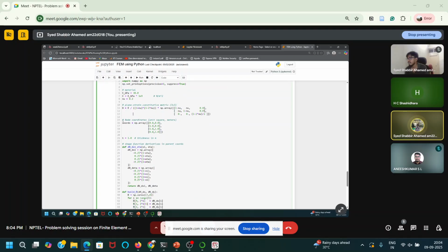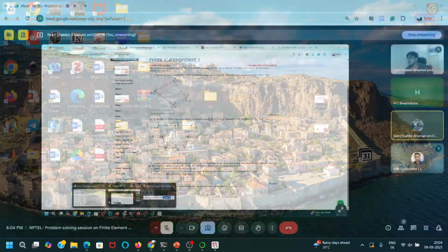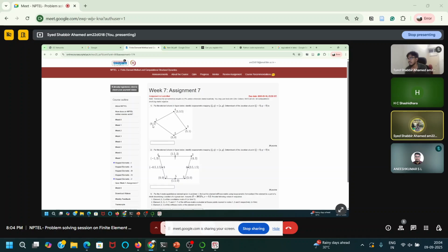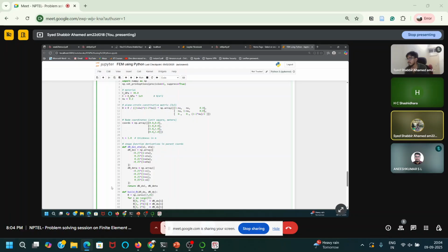And these are all the coordinates. This element which has been given in the Cartesian coordinates is a distorted element. But I would like to make it a regular geometric element by using isoparametric mapping to a natural square quadrilateral which has a regular shape, so that my life becomes easier to do the integrations and all. So first we'll define this square.